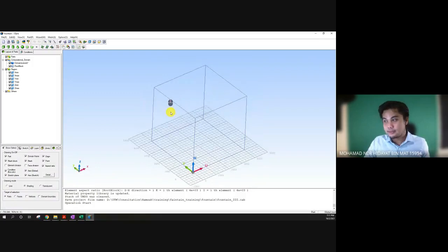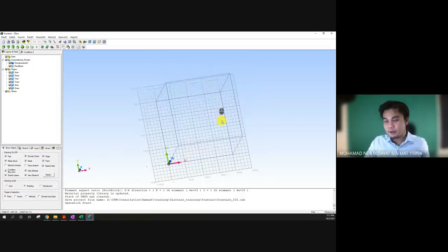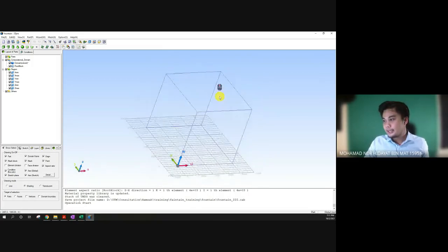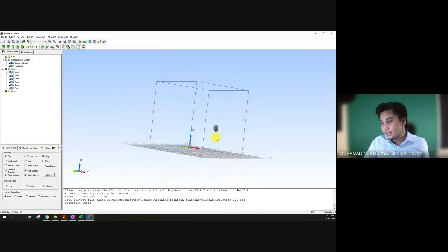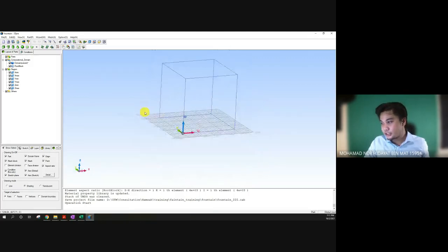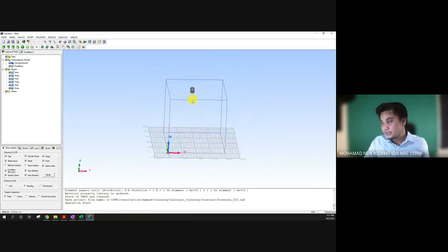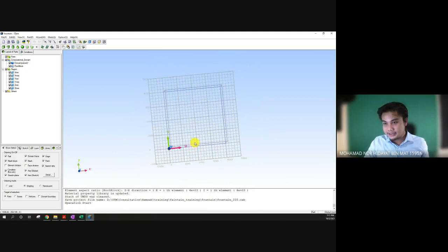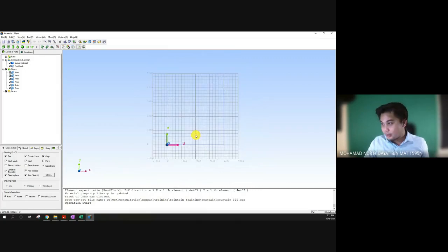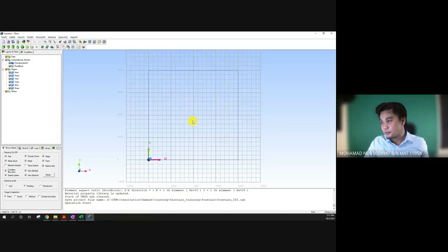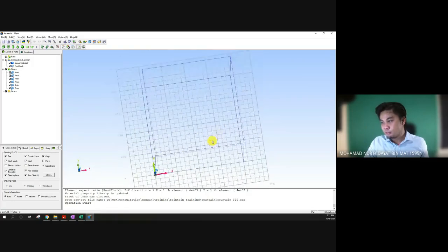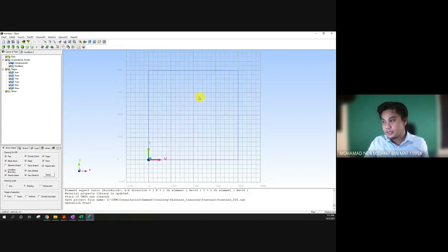All right, so for this case, I want to create my fountain 2 meter by 2 meter. Okay, just select this. This is the sketch plane on the ground, correct position. So just position it like this, and then press A on your keyboard. Can you see it perfectly fits my view? If your view is like this, you press A, it perfectly fits, because I want to draw the cuboid that represents the base of the fountain.